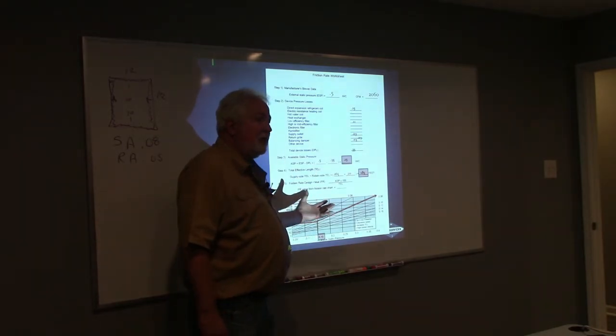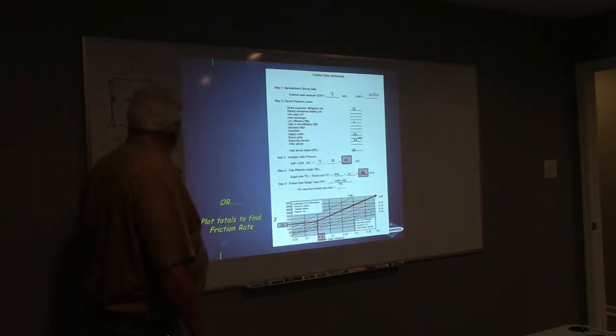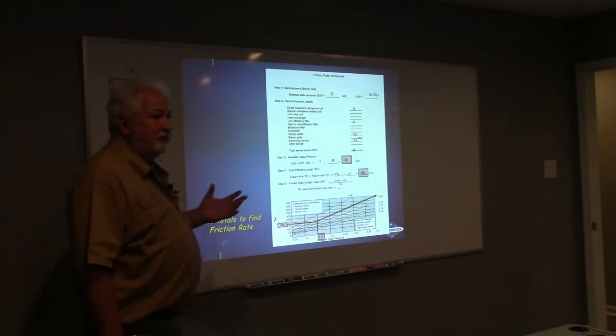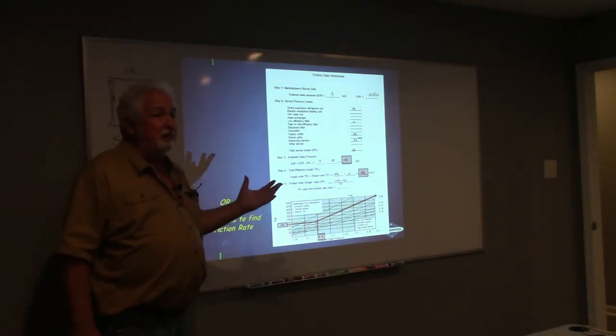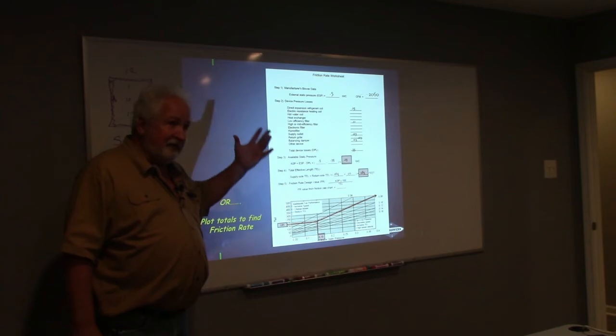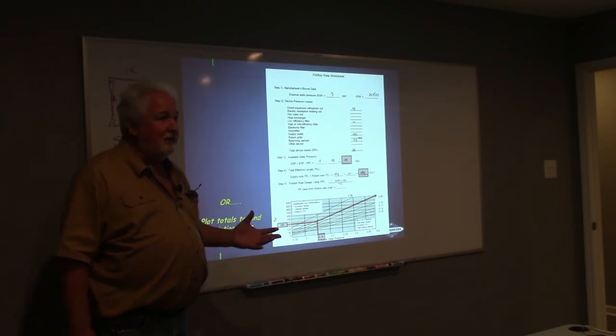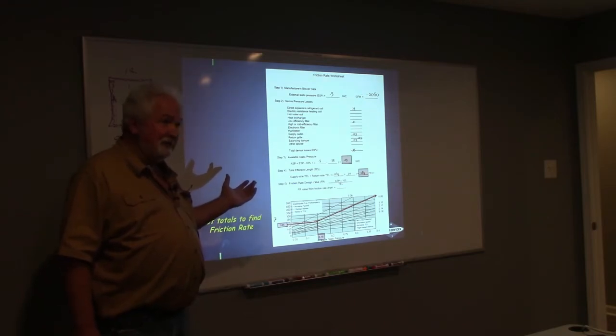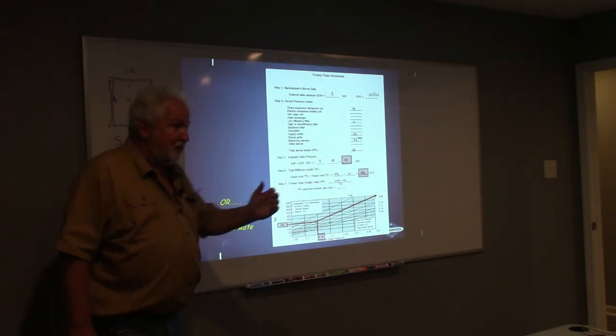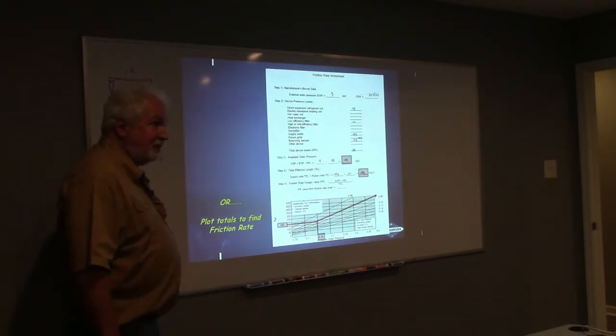So where does the 0.08 come from? It comes from the ugly duct in the house. Should I do this on every job and figure out what I've got where and how? I'm going to say that example I use with the typical ugly duct is probably a typical ugly duct in our market. That's why we ended up with that 0.08 for our supply.